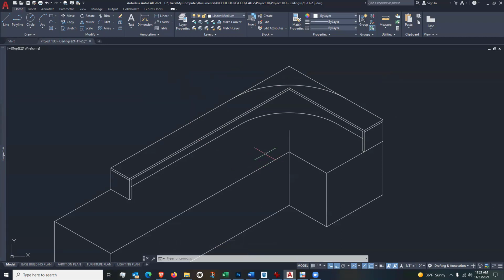All right, while we're in ellipse mode, let's draw the second one. And this one was 36. Now this one that's going to come to here is going to be 24. So go to my ellipse, go to isocircle, go to the top of that line there for the center. And again, it is 24, 2 feet.